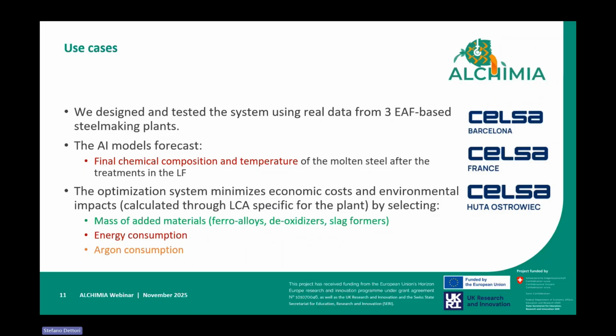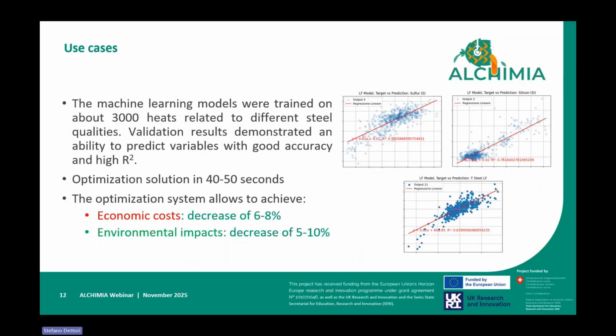The optimization provides some suggestions to the operators in terms of mass of the added materials, so ferroalloys, the oxidizers, and slag formers, the amount of energy consumption for keeping the temperature within the limits, and also the argon consumption in the system.